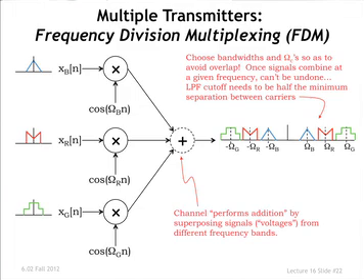Okay, let's now talk about putting multiple signals on a given piece of the spectrum. Okay, this is exactly the situation you have in your lab now. You've got a speaker that can transmit in a certain band, and you're trying to put multiple simultaneous signals on it by using different carriers. So this is what's called frequency division multiplexing, or FDM.